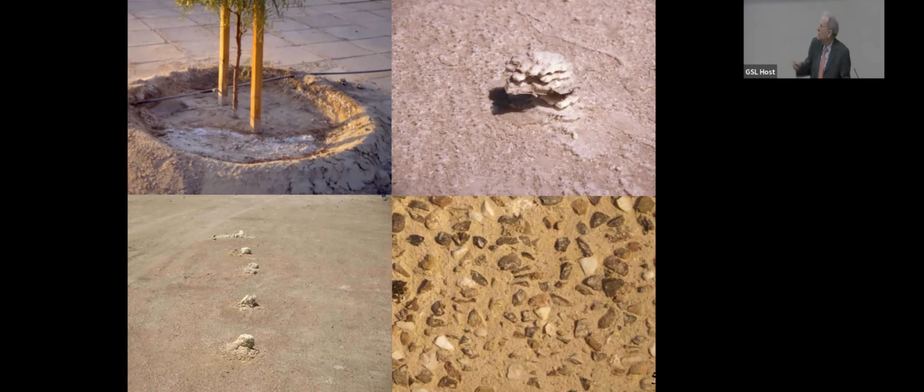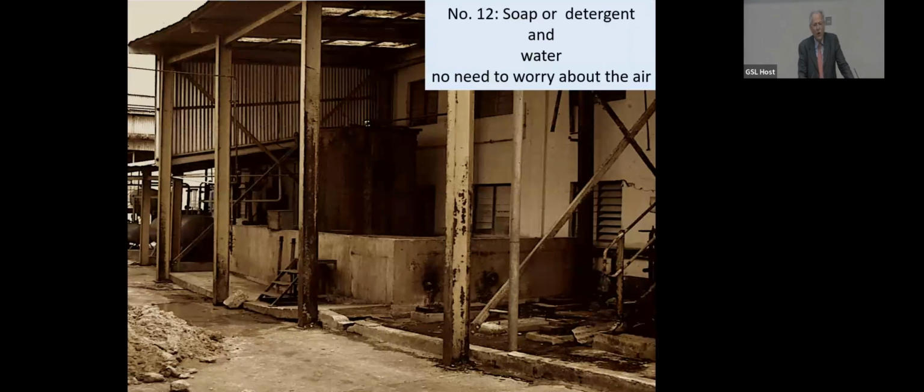I know they're fence posts because in one of them you can find a little bit of the remains of the reinforcing steel, but completely destroyed by wet, dry dissolution, crystallization, dissolution, just little piles of debris. And bottom right is the face of a concrete wall blown off by salt deposition behind. The salt got into a crack, wicked up, pushed it, wicked up, pushed it, and slowly completely destroyed it. So that's just the effect of too much water when you've got salt in the ground.